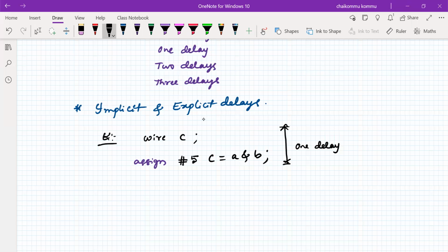Okay, for example, if I'm not writing anything here, what is the delay now? Zero delay. That means that whenever we are computing A and B, it does not produce any kind of delay. Instantaneously we will get the output there. But in Verilog, we cannot say that it gives a very instant output, because of the parasitics. So obviously some delay will be involved in this one.